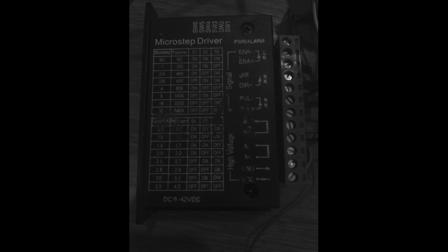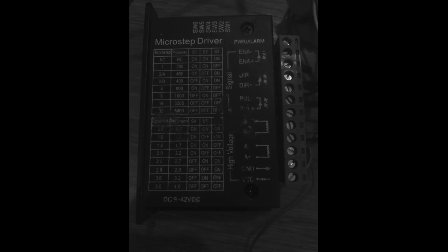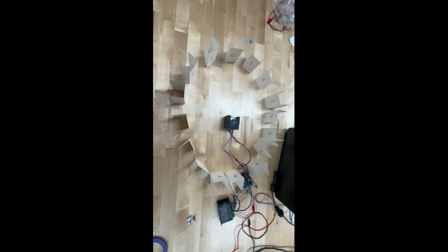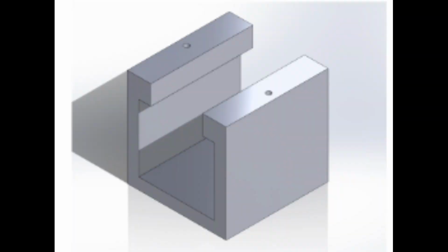There is also a technique called microstepping. By controlling the current going to adjacent coils, the local relative field strength is manipulated. This way, the gear tooth can be held in place between two stable positions. Half-stepping holds in the middle with equal force on either side, while further subdivisions of microstepping use a ratio of current to control where the tooth is held that approximates a sinusoidal AC waveform. This way, the motor can take fractional steps for even more precision.